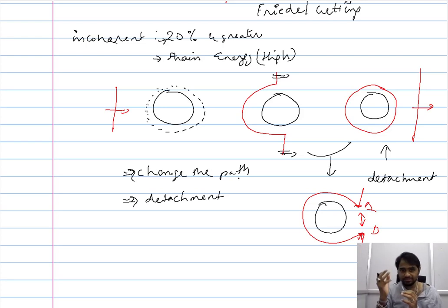So in the previous case, in case of a coherent precipitate, the dislocation is impeded in two ways: one, by the strong elastic interaction, and the other by the fragmentation, or the interaction between the particle and the dislocation, not between the interface but the particle and the dislocation. This interaction leads to the fragmentation, and because of the fragmentation the driving force is consumed, and therefore the rate at which the dislocation propagates is largely compromised.